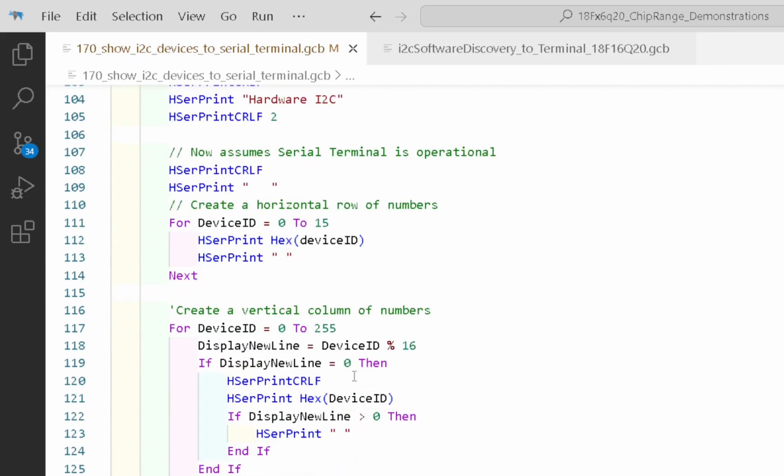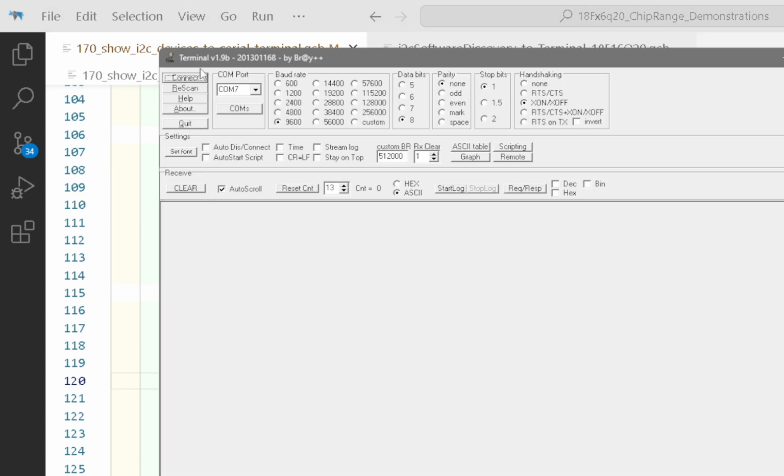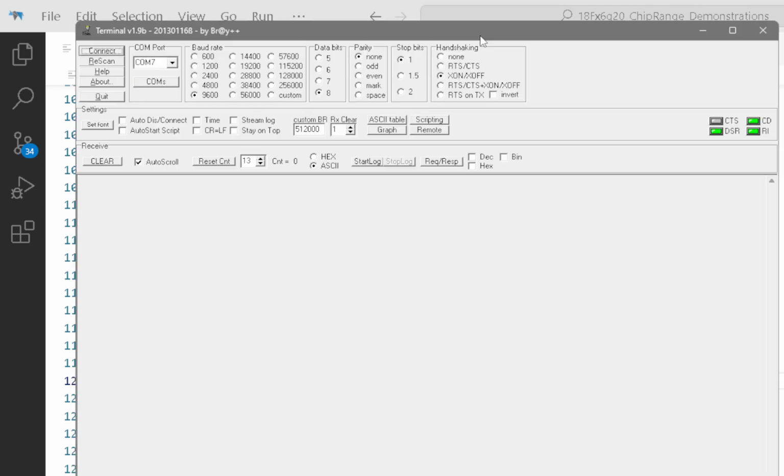And what we're going to do, we're going to run this to see what actually happens. So let me just press function key F9, and that will open up a serial terminal for us, which is fantastic, because that's the serial terminal we're going to be using. If I rescan, top left there, connect to it, I've connected to my TTL buffer, so I've got everything set up now.